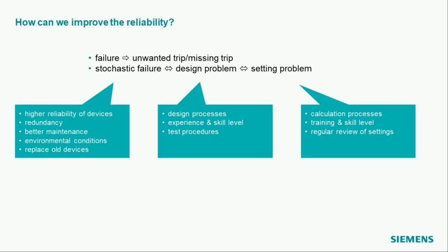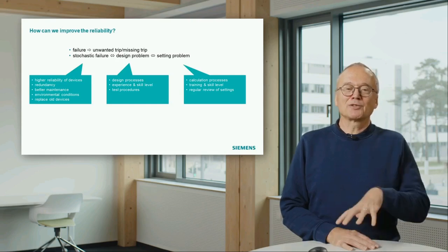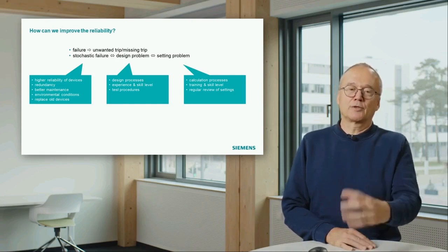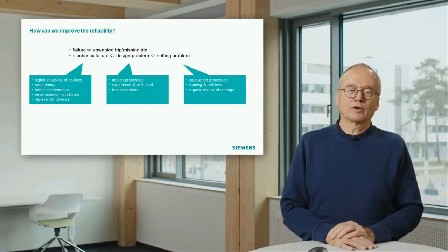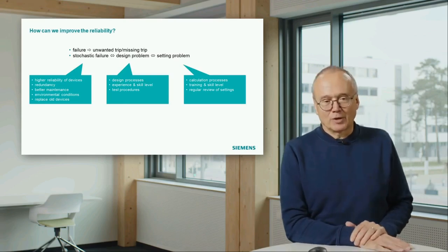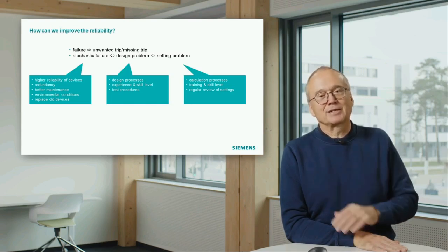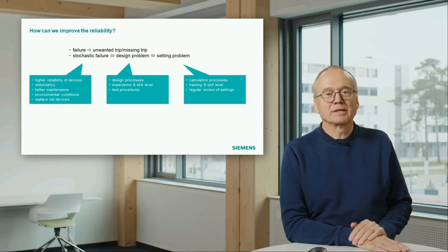So you see, there are different components you have to have a look at if you want to improve the reliability of the system. It is not only the MTBF of the protection relay, and that is the message I want to give with this chapter. And think about this example with front door and back door. I think that's a good equivalent in this case to motivate investment at the right point. So that is the end of the reliability chapter, and after that we will do the part 2 of building a protection scheme.